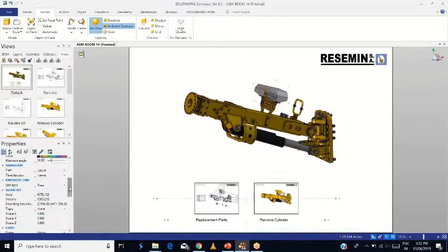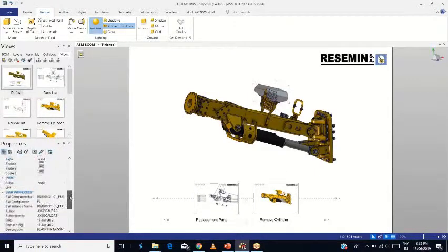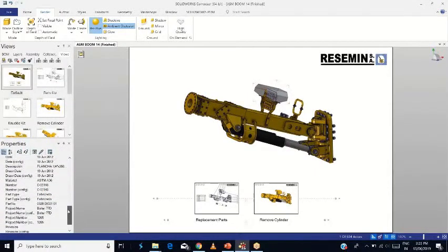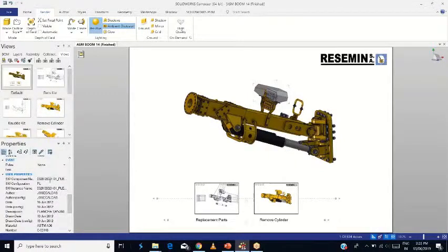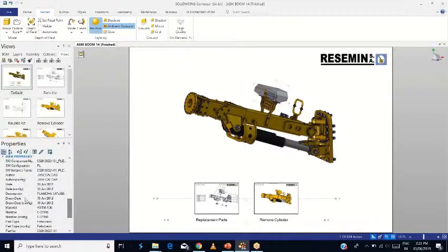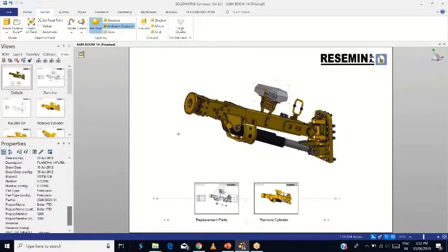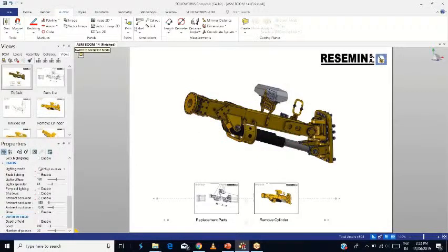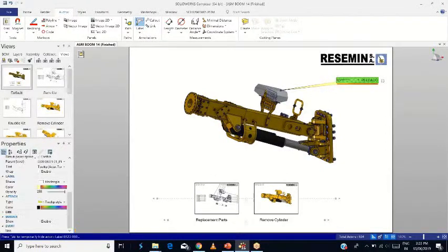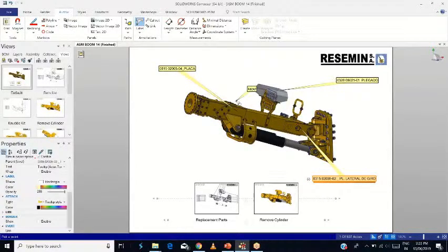It's a completely manipulable software. If you want to scale a component, you can scale it. You can change the area of that. Many options. On the left hand side, you can see user properties, showing how it imported all the meta properties: the date, order, the description, drawn date, material. And if you want to mention that, you can mention that as well. We have many labeling tools in here. So I'm just giving the labels. For each individual part, it simply takes the meta properties. You don't even need to write them individually. And if you want to edit them manually, you can do that.